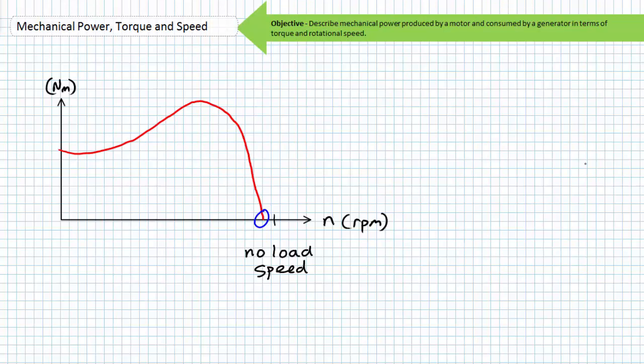Just under the synchronous speed is the no load speed, i.e. the speed at which this motor spins freely when there's nothing to counter its spin. This is a point where speed, N, is pretty high, but torque, T, is 0. Notice in the case of a three-phase squirrel cage induction motor, its no-load speed is just under the synchronous speed, meaning even if it's unloaded, the rotor is ever so slightly lagging behind the rotating magnetic field produced by the stator. As we'll learn in later lectures, there must be a lag or slip behind synchronous speed for a squirrel cage induction motor to work at all.